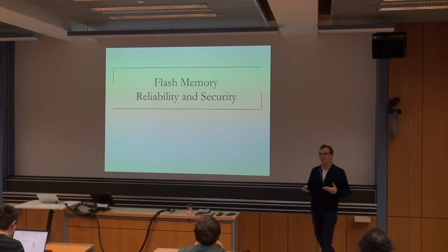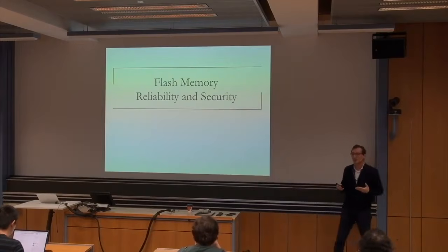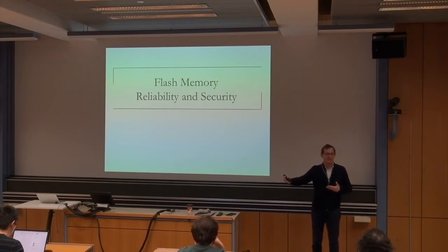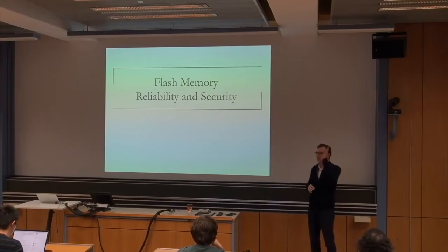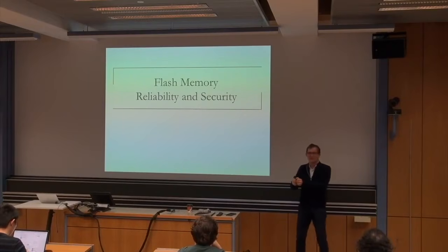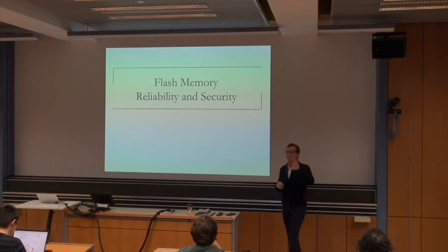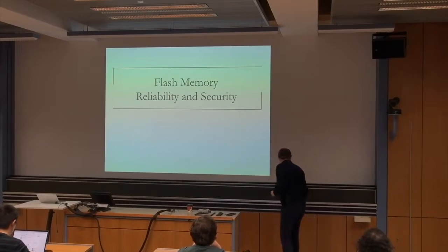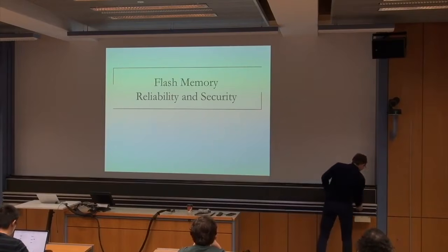So one of the big jobs of the flash translation layer is to keep track of what block exists where, because it does a lot of these remappings. You have a logical block address that gets remapped to physical locations, because whenever you modify, you actually cannot directly modify, you need to remap it. That's the idea. Now, okay, you remap this page from this location, from this block, to this other block. Actually, let's give an example over here, if we can.